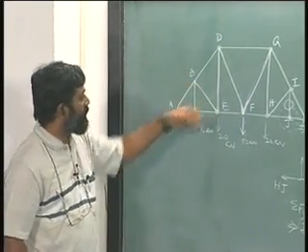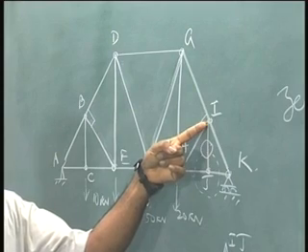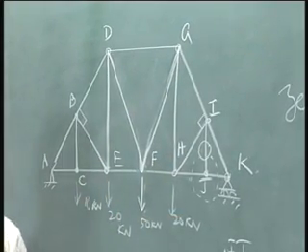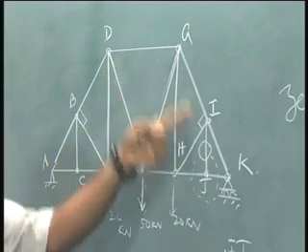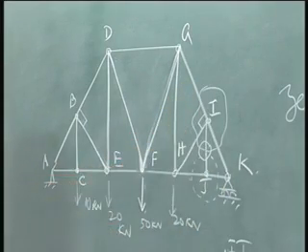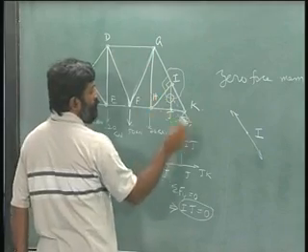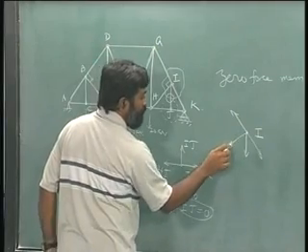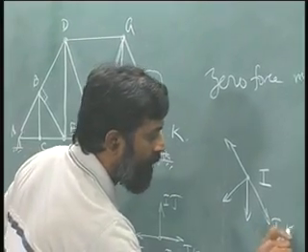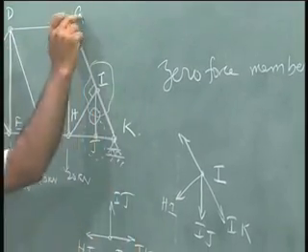Let us say this is connected in such a way that this is perpendicular. Is this a zero force member? Well, if I had found that IJ is a zero force member and this is perpendicular to this particular set of members KIJ, and if I draw the free body of this particular joint I, I have 1, 2, 3 and 4 forces revealed. Mind you, I am always drawing in such a way that all the forces emanate from this joint. So, now I just have to number, this is IK, IJ, HI and GI.